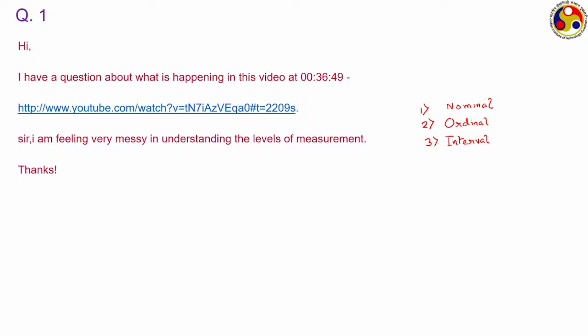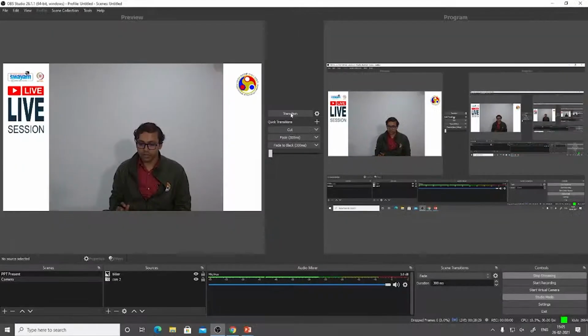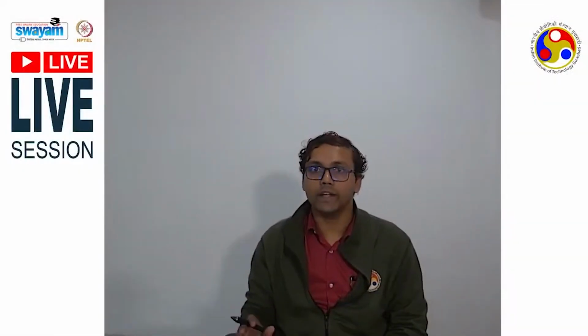When we devise the Celsius scale, we decided that the ice point should be given a mark of 0 and the steam point a mark of 100. Then the distance between these two is divided into 100 equal divisions, and therefore the length of each division is 1 degree Celsius. However, for the same 2 points in the Kelvin scale, the ice point is 273.15 and the steam point is 373.15. In the Fahrenheit scale, they are 32 and 212, with 180 equal divisions between them.